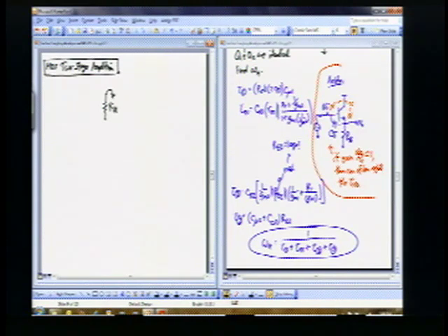So this is a drain resistor RD1 going into MOS device M1. And I'm going to ground M1. So that's basically a common source type configuration. I'll go into this with a voltage source that's driving a resistance RS.